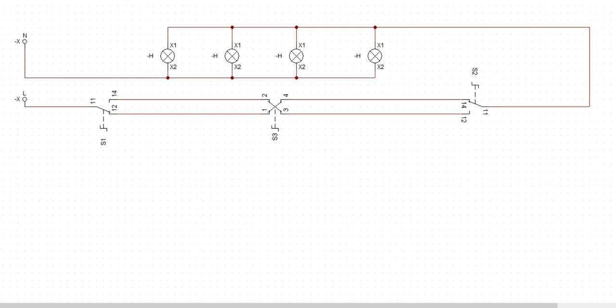Let me get a sample again. If you need four position, now, like now I have three position. If you need four position or how many positions, see what you do. Let me repeat again, pay attention please. If you need to control lamp or lighting system or lighting illumination from two positions, you use this one gang two-way, two of them to control.